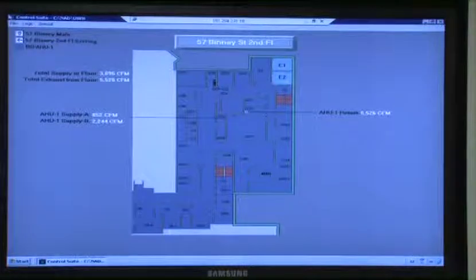Yeah, I mean, he's just starting to go through and measure stuff, and the balance is recalculated. All right. This was not on the high end of his priority list because it really didn't affect his balance report. This was for us only, I mean for the automation system. I think it was something he left towards the end of his process. There's a thing that calls for a construction exhaust for each floor, and there's another one that's for isolation, but this level doesn't have an isolation. And I don't think we monitor flow on construction either.